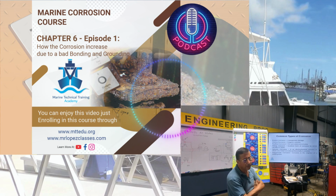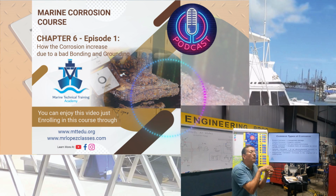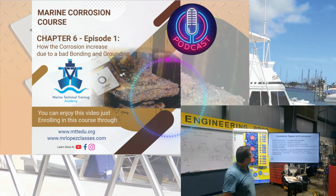The clean signal enters into the main breaker of the AC panel. The ground is outside. In the hotline and neutral you insert the isolator transformer. The function of the isolator transformer is to clean the signal, and the function of the galvanic isolator is to block the intrusion of bad currents through the ground. That's the main difference.